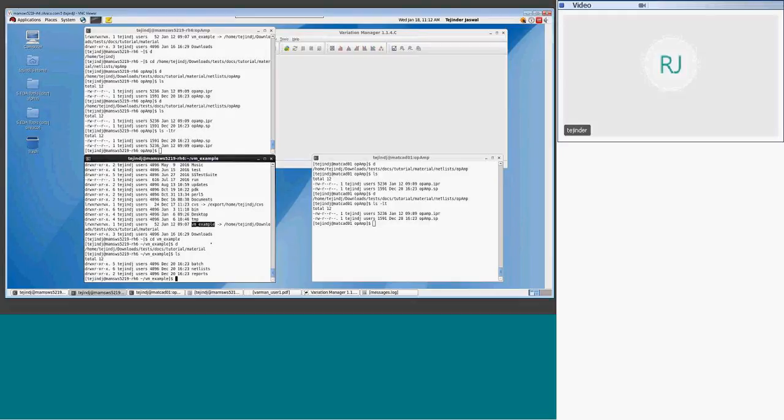So I don't know, you still can run that, but again, in the end, you need to see the results, to probe and other things. So you can do that manually. But it's done in the tool, so you don't have to do that. If there is a failed variation, like the simulation failed, from the tool you can see the waveform and all the measure statements, and you can bring the wave viewer in the design through the variation manager.